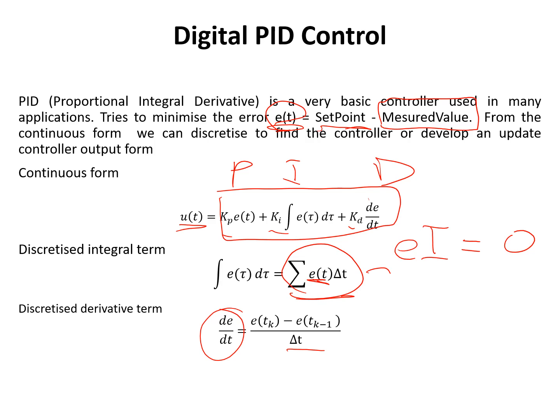And the difference would be that, since our PID typically assumes a linear system, you can have the same controller design with either duty cycle or the voltage output. The only difference would be your gains will be slightly different because you're now accommodating. It's basically like having an additional gain in the system.